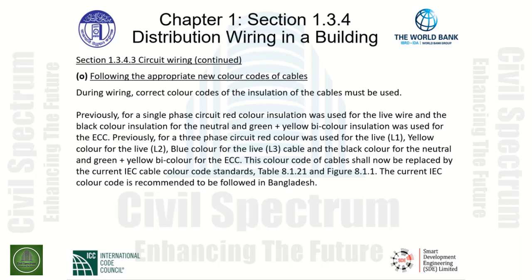Previously, for a three-phase circuit, red color was used for the live L1, yellow color for the live L2, blue color for the live L3 cable, and the black color for the neutral, and green plus yellow bicolor for the ECC. This color code of cable shall now be replaced by the current IEC Cable Color Code Standards.